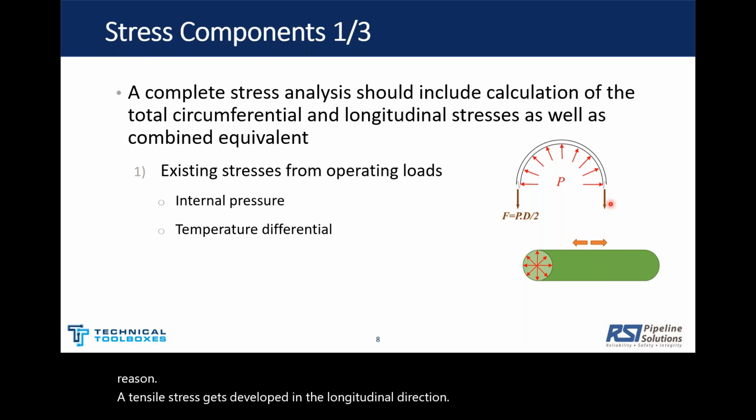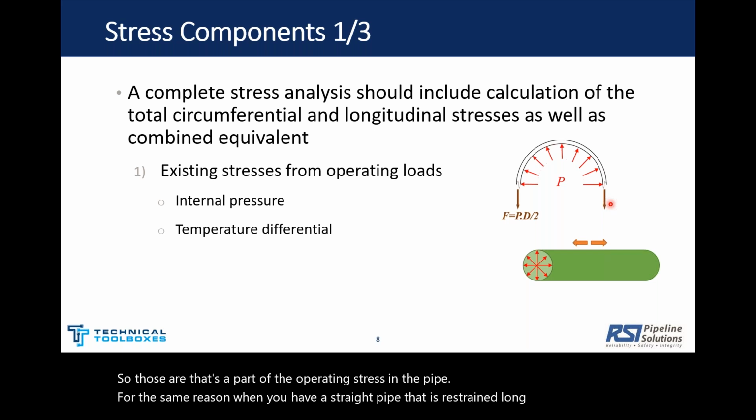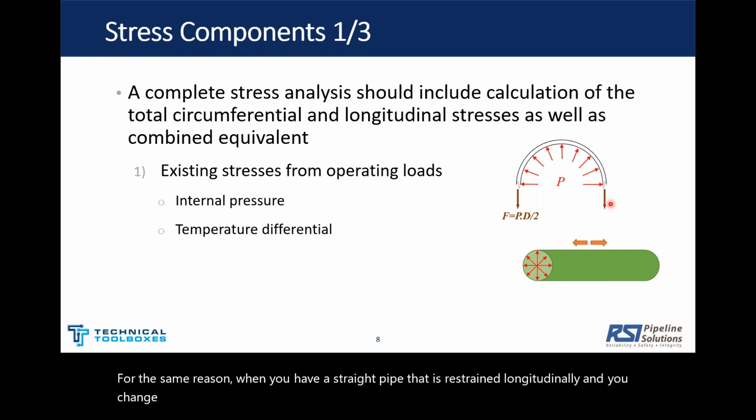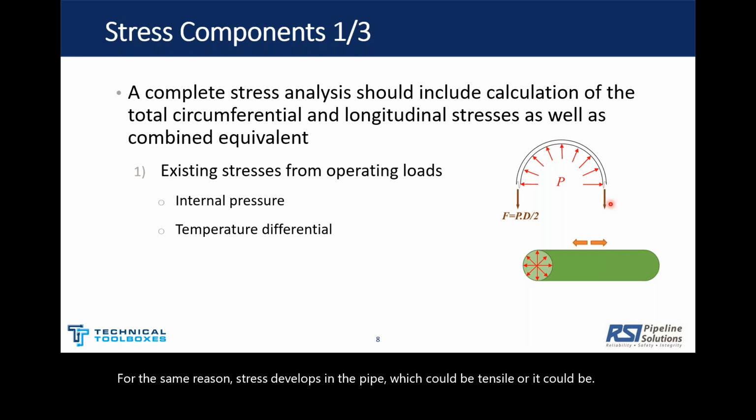So that's a part of the operating stress in the pipe. For the same reason, when you have a straight pipe that is restrained longitudinally and you change the temperature in the pipe, a stress develops in the pipe, which could be tensile or it could be compressive, depending on the change.